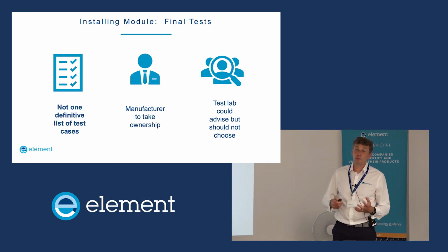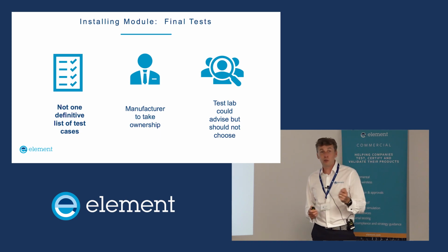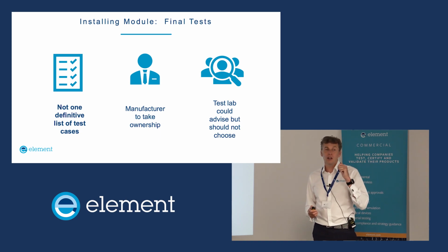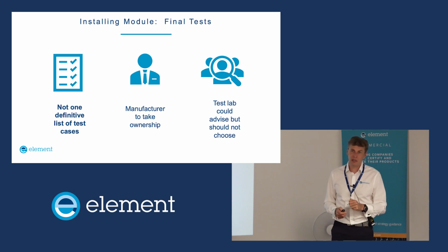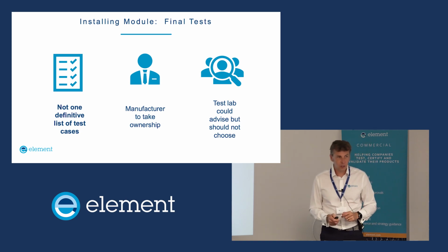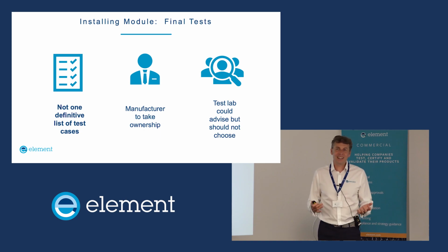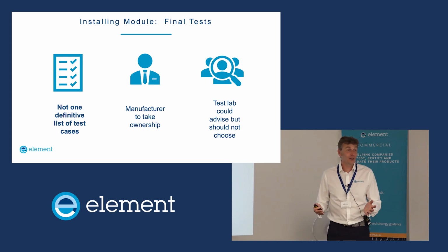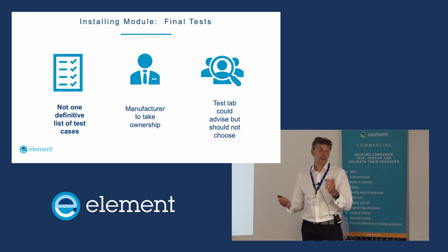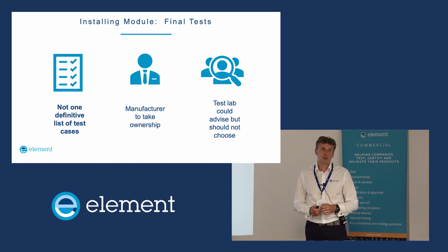Often a manufacturer will phone us up and say, we've installed a radio module into a product. What tests do you think we should repeat in the transmit mode? And as a sensible lab, we should say, well, it's up to you. What do you want to do? Actually, manufacturers don't want to hear that, and it's not a conversation they want to have because they know that they could phone somebody else up and the other lab will go, oh yeah, just repeat transmitter tests, so the spurious emissions test, that's fine.